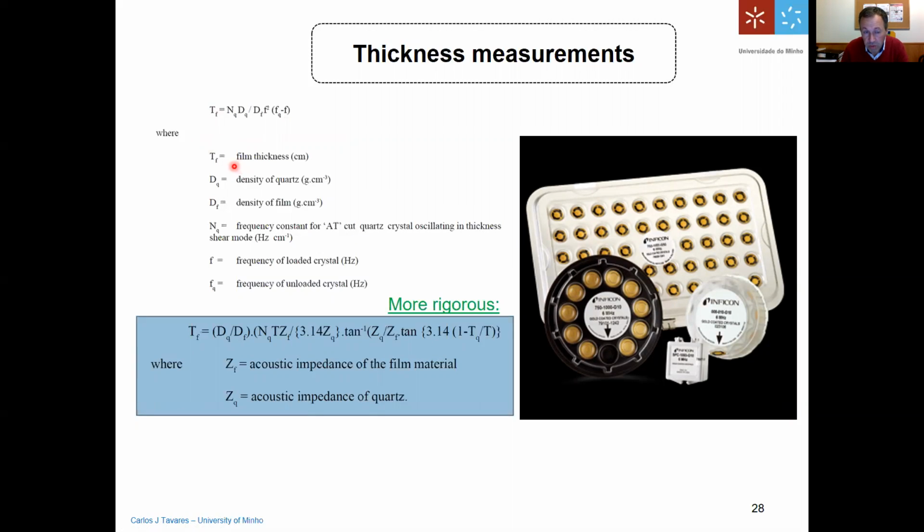You need to know something beforehand. The thin film thickness is normally measured in angstroms or nanometers, but you can also measure it in centimeters. That doesn't make sense because normally the films that you produce are angstrom size. You can make 20 angstroms or 20 nanometers, at most 200 nanometers or 2 microns in sputtering. You really don't make very thick films. Maybe with thermal evaporation, you can do several microns, but you will never do something which is millimeters. It's too thick. It will grow too much stress inside the film, and the film will spall, will not adhere very well to the substrate.